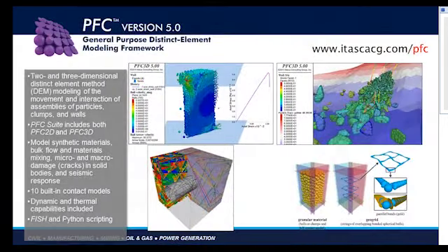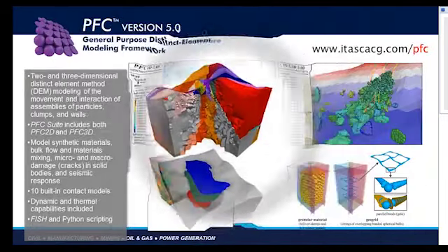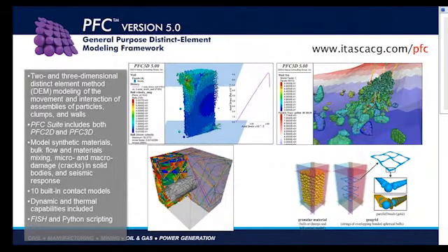Okay, and this takes us to another form of the distinct discrete element, that's Particle Flow Code, PFC. With PFC, really, the base is that you go almost to the grain size, even though not completely, but you model these balls and interaction of the balls with each other, and you calibrate this artificially created material to match, let's say, the UCS test, and then use those parameters that you achieve through calibration to build this material.